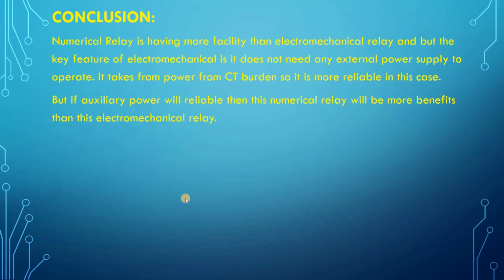So the conclusion of this experiment, what we did in part 1 and part 2, is that this numerical relay has more facility than the electromechanical relay. It can combinedly operate as 3 electromechanical or 4 electromechanical or multiple electromechanical relays as one relay. It can replace the number of relays with 1. So the circuit will be a little bit easier, and it reduces the complexity of the substation design,